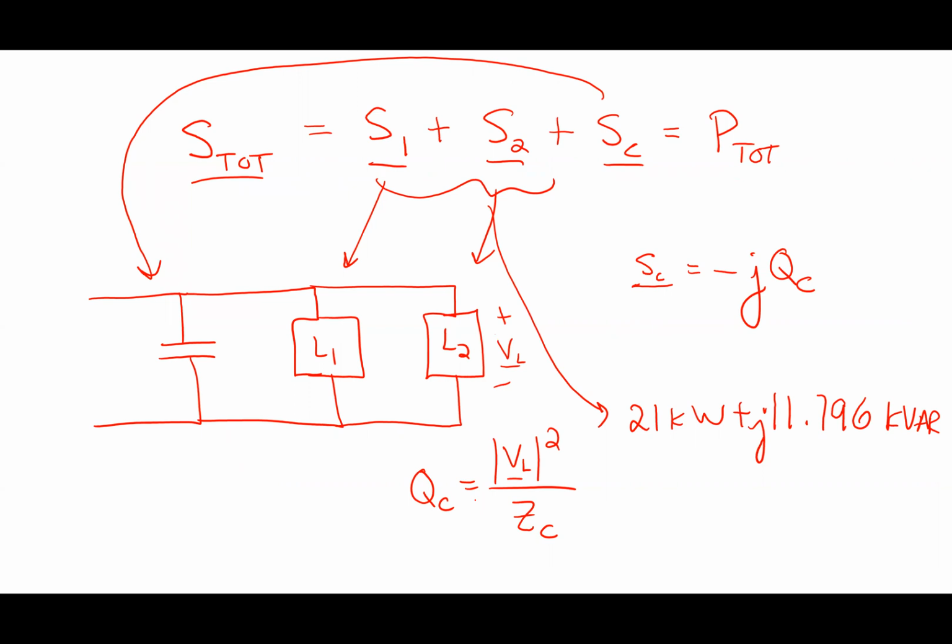Okay. So if I do this, I work out that Z sub C is equal to 3.6677 ohms. So how do I relate that to an actual capacitor value? What do I know about Z sub C, particularly its magnitude? Yep, 1 over omega C. And I told you the frequency was 60 hertz, so I know what omega is, and you can figure out C.